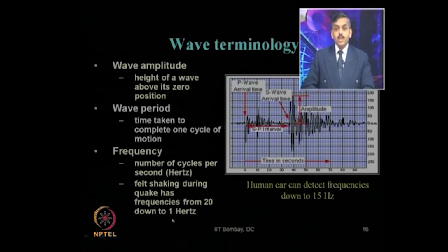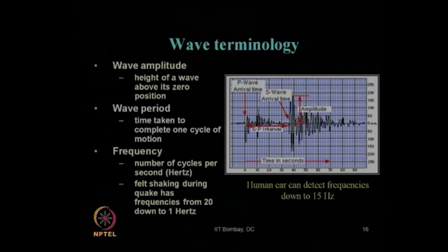I will try to correlate this to other dynamic problems. What are the basic differences of frequencies? When we talk about the design of machine foundations, or machines running at various frequencies, their frequency ranges are very high compared to earthquake frequency. Also, if we want to handle the design of subgrade below a railway track, then we have to consider the dynamic frequency caused by the movement of the railway.